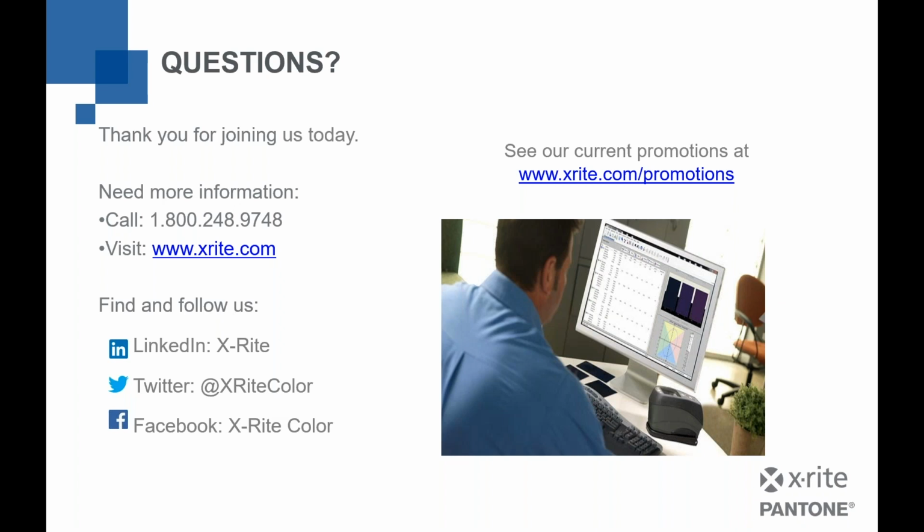Along that same question, how do you measure sample thickness? Generally, what you're going to use is a micrometer. We don't sell micrometers, but on any scientific website you can get it. You're measuring the thickness of a substrate that you're putting down, and then the ink film, paint film, or you're measuring the thickness of the plastic chip. It's just a micrometer. It can give it to you in inches, in mils, in millimeters. They're widely acceptable out there. They've been used for years.